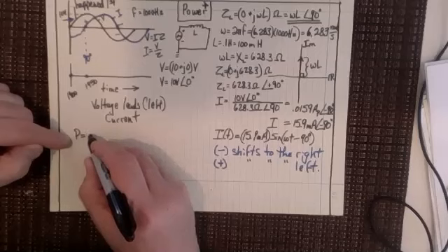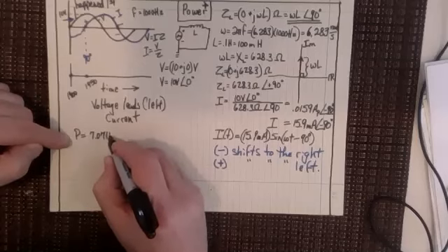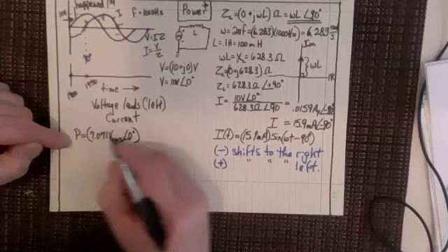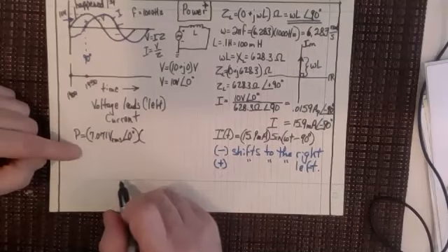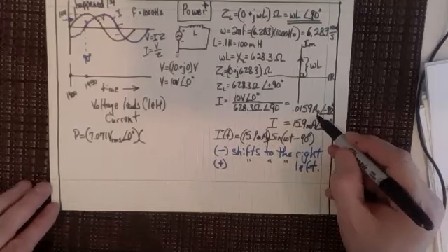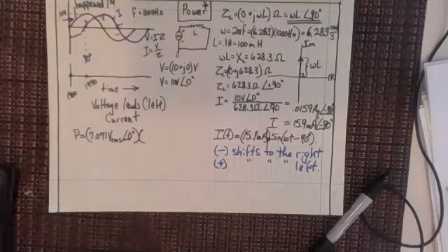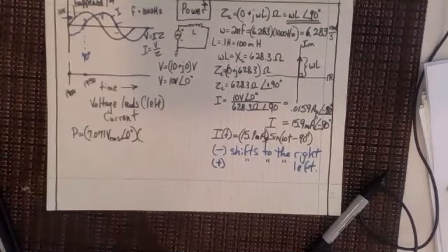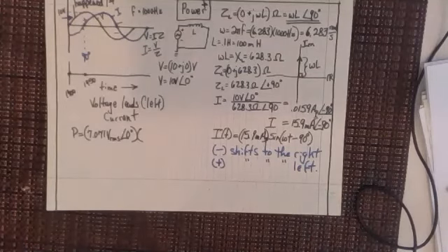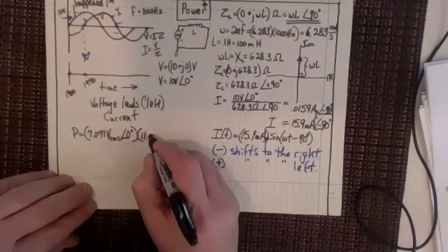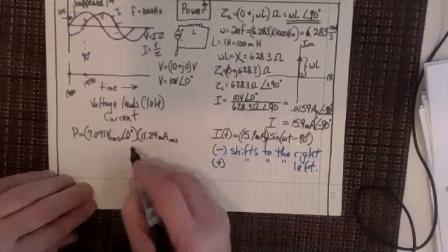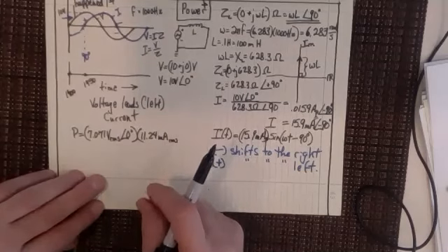So if I'm talking about V, I'm talking about 7.071 volts RMS, right, at an angle of 0 degrees. And then I, which I've got over here, is 15.9 milliamps, but of course that's milliamps peak, isn't it? There's always peak here. So we've got to multiply that 15.9 by 0.7071. 15.9 times 0.7071 equals 11.24. So I've got 11.24 milliamps RMS. Remember, I'm using milli here, so I have to always put in times 10 to the minus 3.